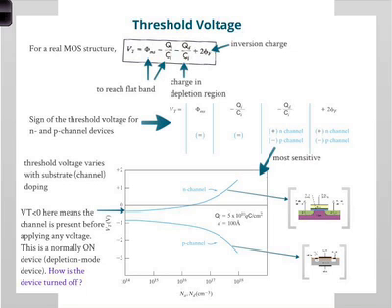So what you're saying is that, remember, the depletion region is almost entirely in the substrate, right? And the reason that is the case is because the substrate is lightly doped. Okay? If you heavily dope it, then the impact of the depletion region goes down, and then the control from your gate goes down, in a sense. You have to think about that effect, how the gate is controlling that channel.